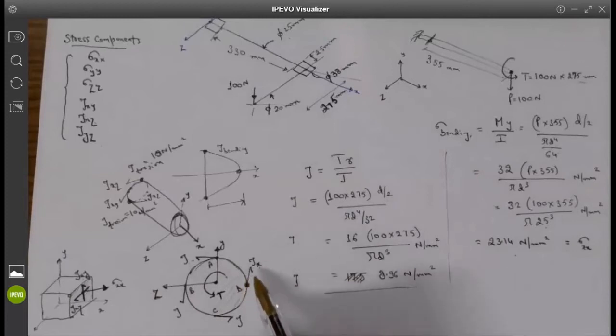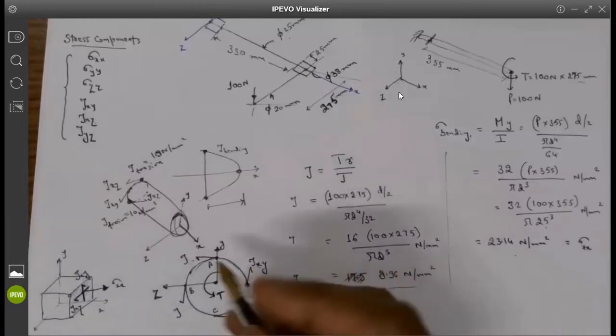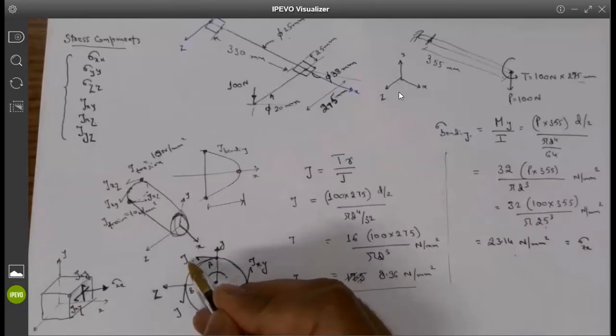And the second subscript represents the direction along which it is acting. In which direction is this stress acting? The Y. So this is tau xy. Do you see what I'm saying here, guys? Yes. And what would be the subscript for this tau? XZ. XZ, perfect. You guys now got that.